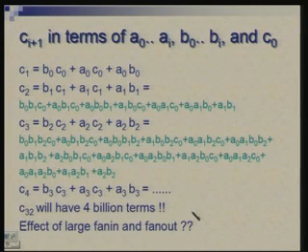Another way of explaining these P's and G's is that the generate term is here, which we have abbreviated as G0, and the propagate term is essentially taking this as a common factor. What is getting ANDed with C0 is A0 plus B0. So, that is the propagate term. Once we have taken these out, in the process we have made things slower because we have added more stages, but we have got a circuit which is reasonable and feasible.